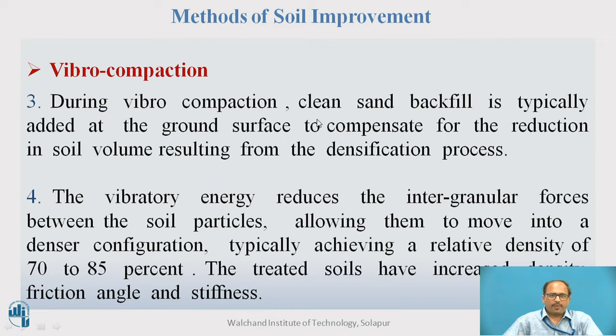During Vibro-compaction, clean sand and backfill is typically added at the ground surface to compensate for the reduction in soil volume resulting from the densification process. What happens during Vibro-compaction? Some volume of soil mass is reduced. That's why we refill some sand backfill to maintain the density of the soil.